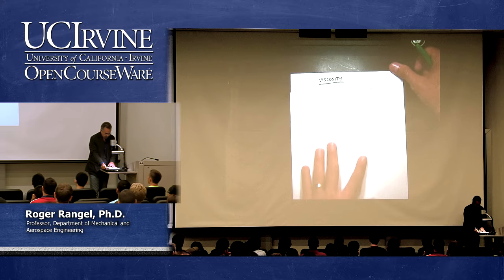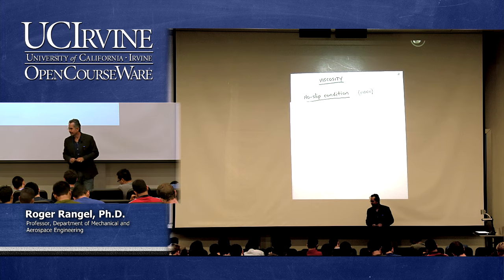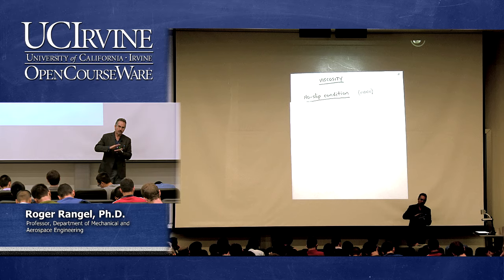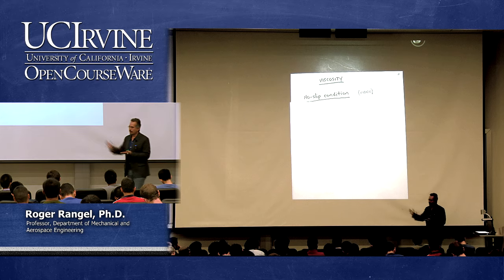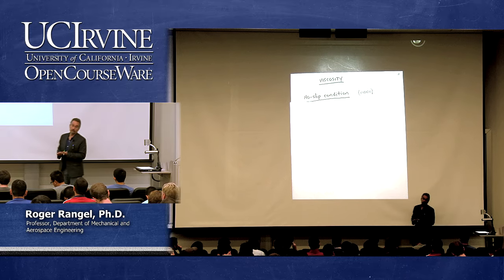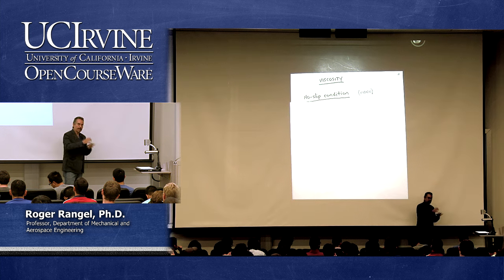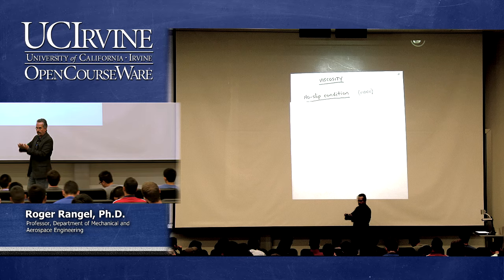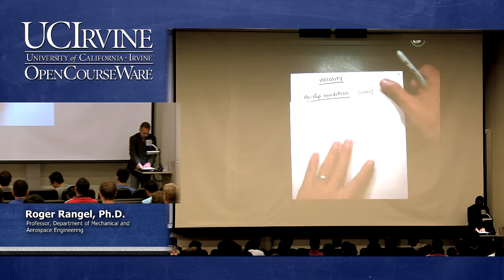What you saw in that video is what we know in fluid mechanics as the no-slip condition. What the no-slip condition is telling us is that the fluid that is in contact with a surface will have the velocity of that surface. In this case, the bottom surface was not moving, so the fluid in contact with that bottom surface is not moving. That's the no-slip condition, and it's a well-verified fact that fluids will do that. So if I have flow over a wing, then the fluid that is touching the wing is not moving with respect to the wing, right at the point of contact. We know that as the no-slip condition. So that's what we saw.